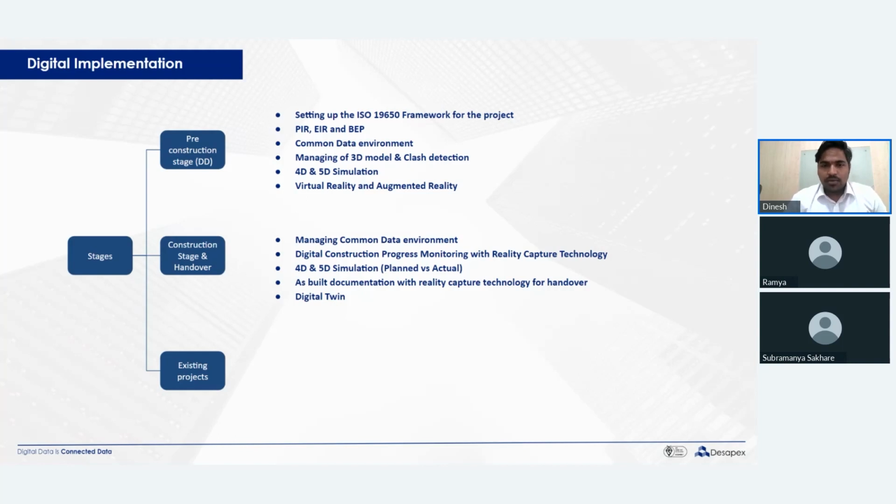It's very difficult to measure manually, and it may not be accurate. That's where reality capture laser scanning technology comes into the picture, where laser scanners help us capture the present as-built conditions, compare them with the developed 3D models, and update the 3D models. At the end of the handover, you have the BIM model updated as per the site conditions as well.